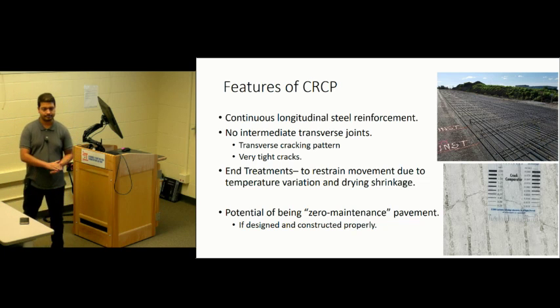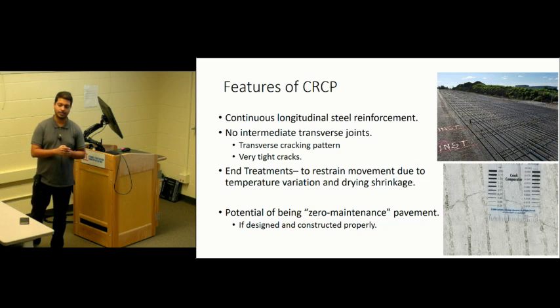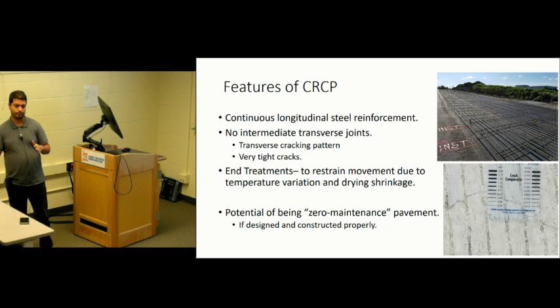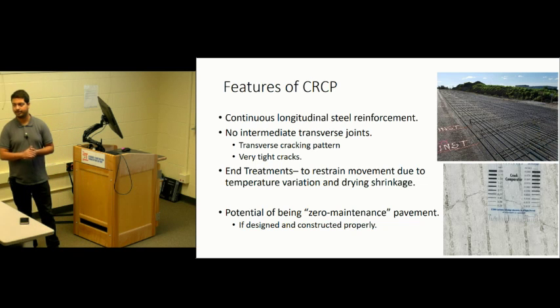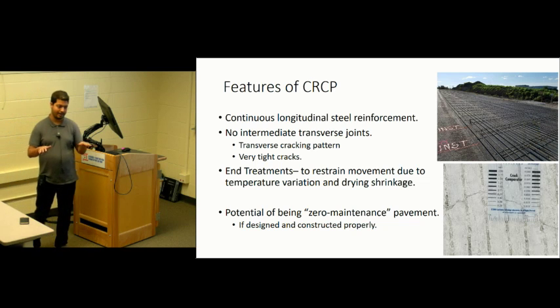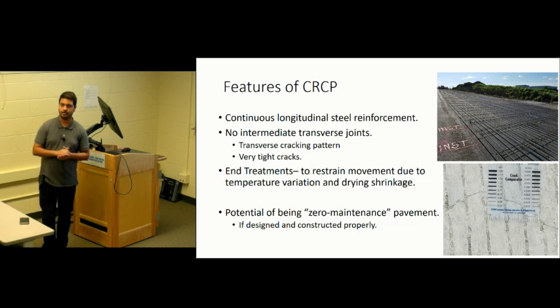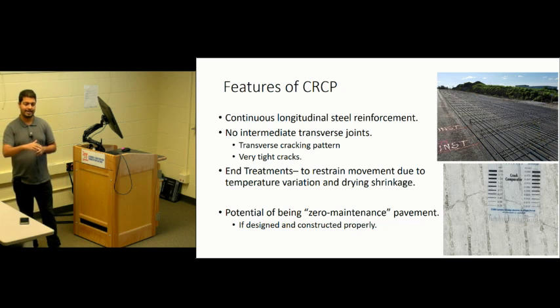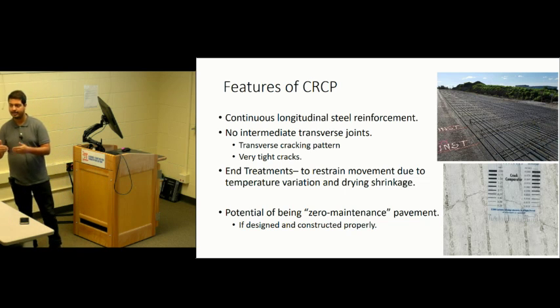Are the sensors recording the information all the time continuously, or do they have some kind of system where they wake up to record and then sleep? Yeah, they wake up every 15 minutes to 10 minutes. It depends on what sensor we are talking about and power requirement. If we use a higher sampling rate, then it consumes more power. To balance that, for strain gauges and thermocouples we have done around 10 minutes. For the dynamic strain gauge, we have not activated it, but another good thing is we can make the dynamic strain gauge act as a static strain gauge and collect data every 15 minutes.